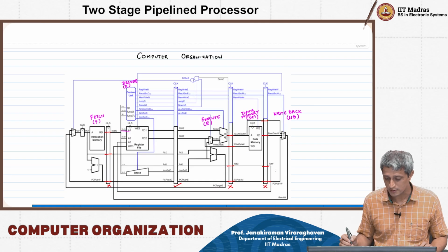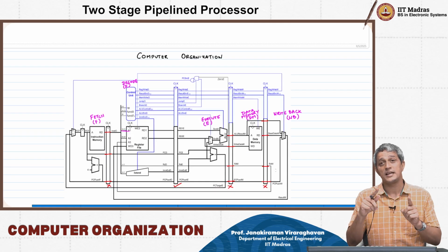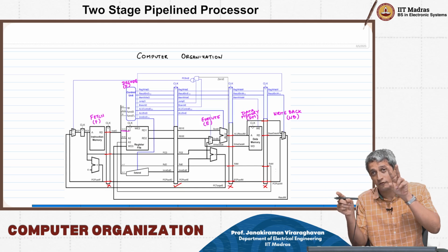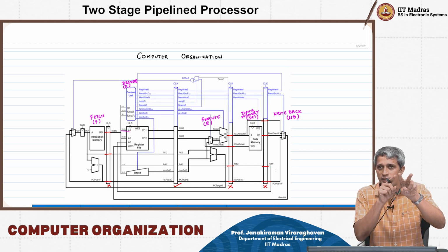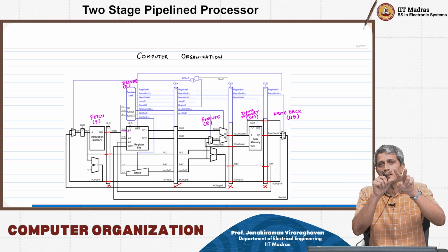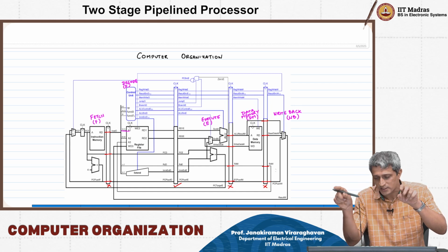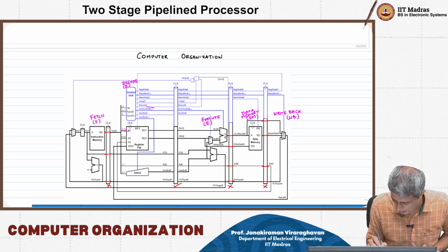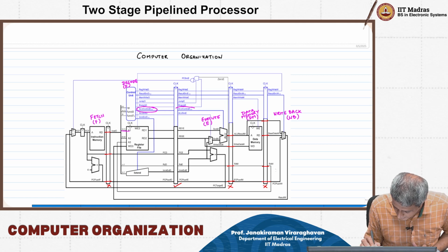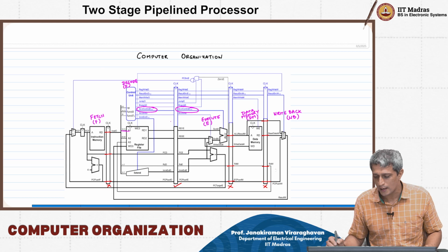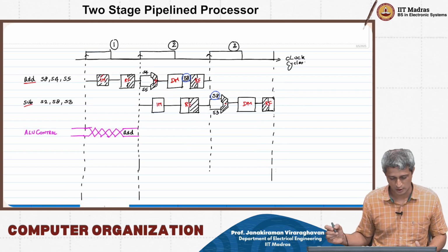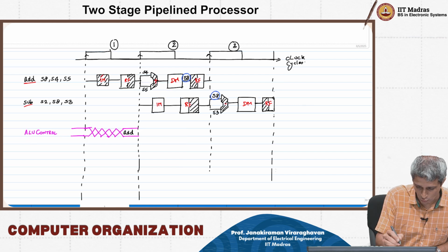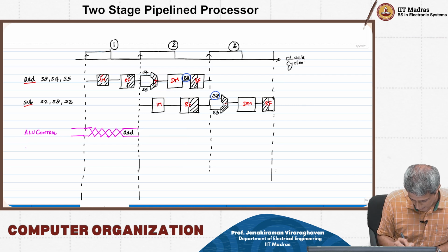In fact it is in the next cycle that the instruction is going to get executed. So the fact that this is an add instruction needs to be transmitted across the flip-flop to the next signal, and that's why this ALU control here gets registered and comes out as ALU control E out here, and therefore what you have to now keep track of is ALU.